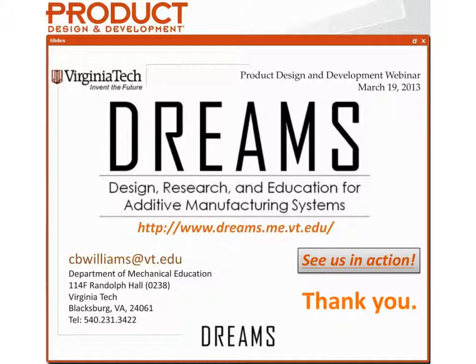Okay. So with PolyJet, I will tell you there's two different finishes. There's a glossy finish and a matte finish. So depending on which one of those you choose, you're going to get a different result. And again, as we referenced before, with a 16-micron layer printing capability, when you're printing a curved surface with PolyJet technology, you get very, very smooth surfaces. So it's a little tough to quantify.